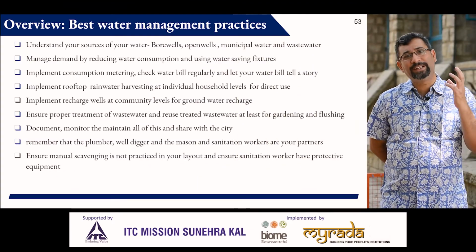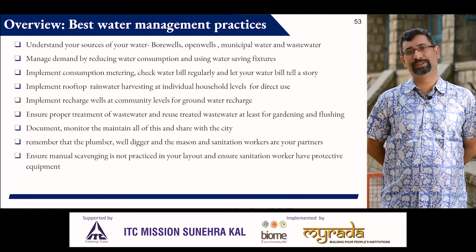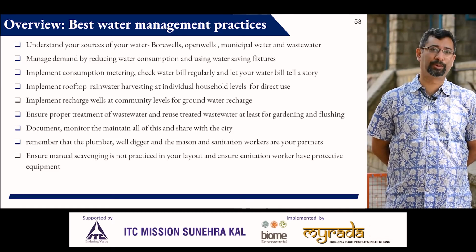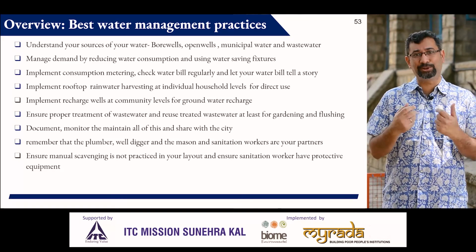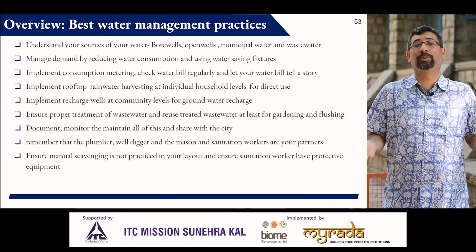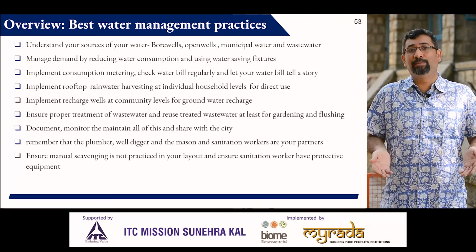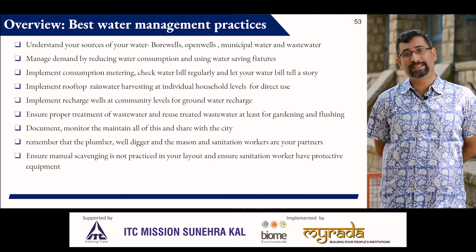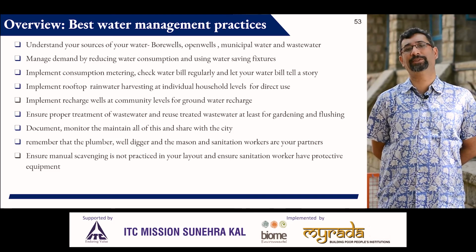Just to summarize all the good practices in water management that you can employ, think of the entire journey of water, from where it begins to where it ends after you use it. So you begin with your sources. It may be your bore wells, your wells, municipal supply, even tanker water supply. But do you understand your sources? Do you understand your well? Do you understand your bore well? How much does it yield? Which bore well is the most important bore well in your layout or your apartment? These are very important things to capture, things where you have to invest in understanding. So that's your first step in good water management.